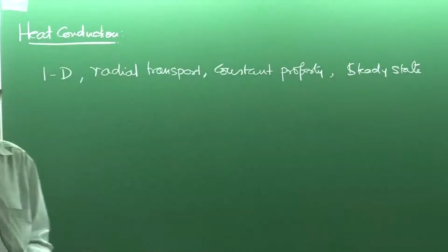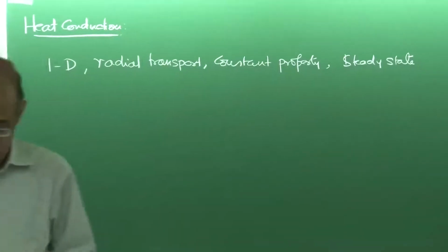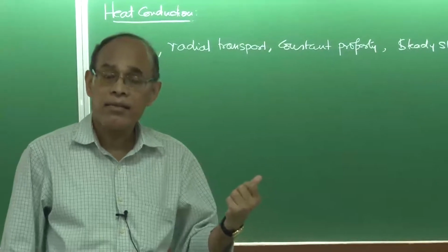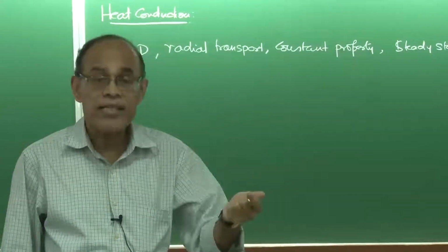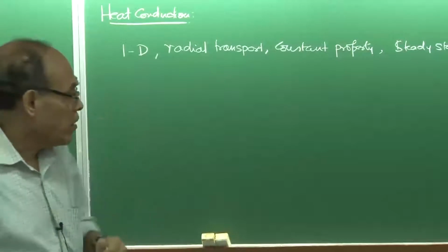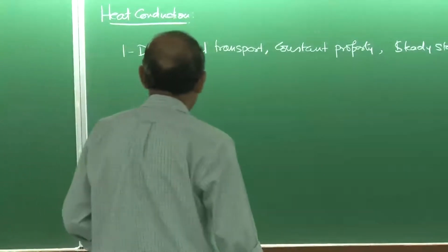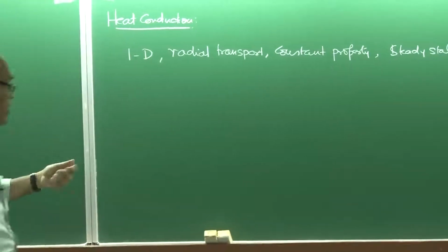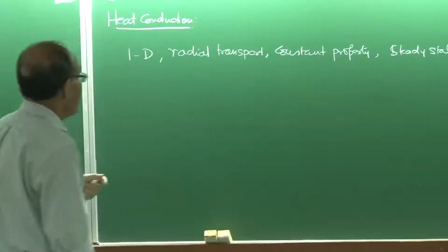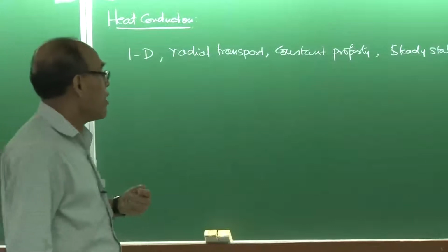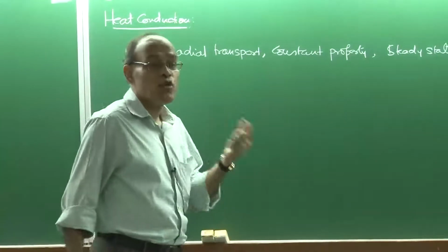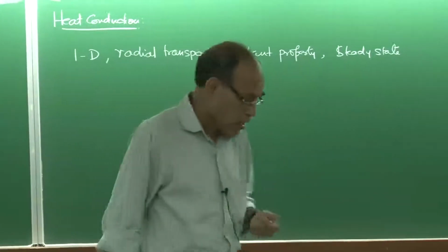So, the governing equation that I wrote, which had 3 different terms: one is the unsteady term on the left hand side, equal to, on the right hand side, I had the divergence term, or the gradient term rather of temperature, and there is the heat flux terms basically, and I also had the volumetric rate of heat generation.